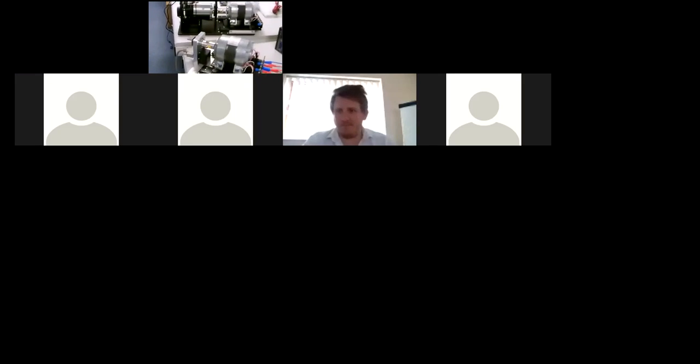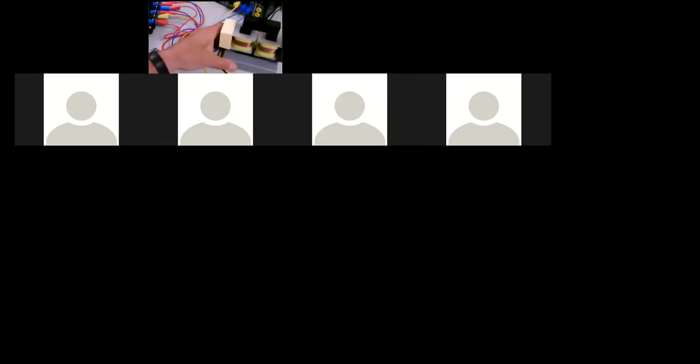Great, okay, John. Okay, so this is our control box, and I've got some standard 4mm connectors. And this is just a small demountable transformer set. With a particular single phase application that we've written, we can inject a single phase into the primary, and we can monitor the current and voltage in the primary when the secondary is open circuit and when it's short circuit.